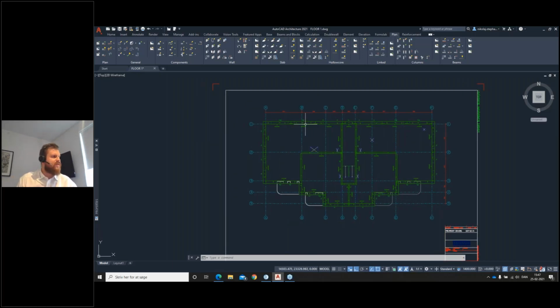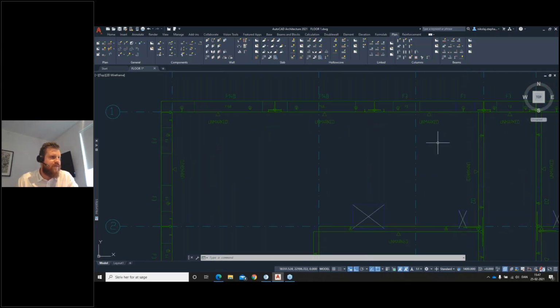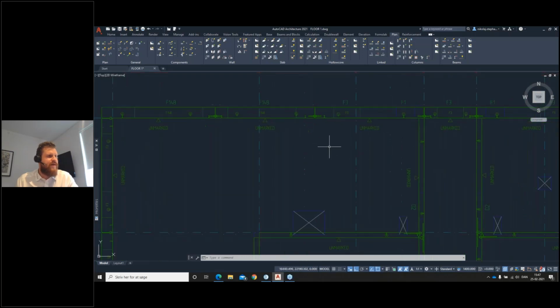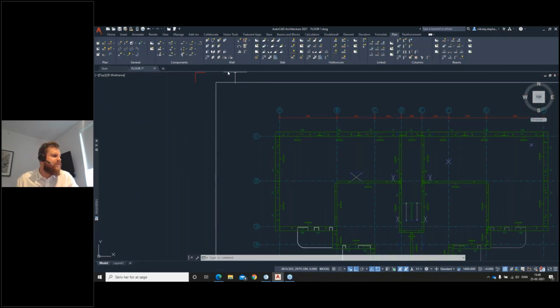So what I will do is I need some numbers. I need some element marks on these elements. As you can see, this is unmarked, unmarked, unmarked. That basically means it's not saved yet. We haven't given it an element number. To make a drawing, of course, we need to give it an element number. So what I do here is I click, I want to save my walls.